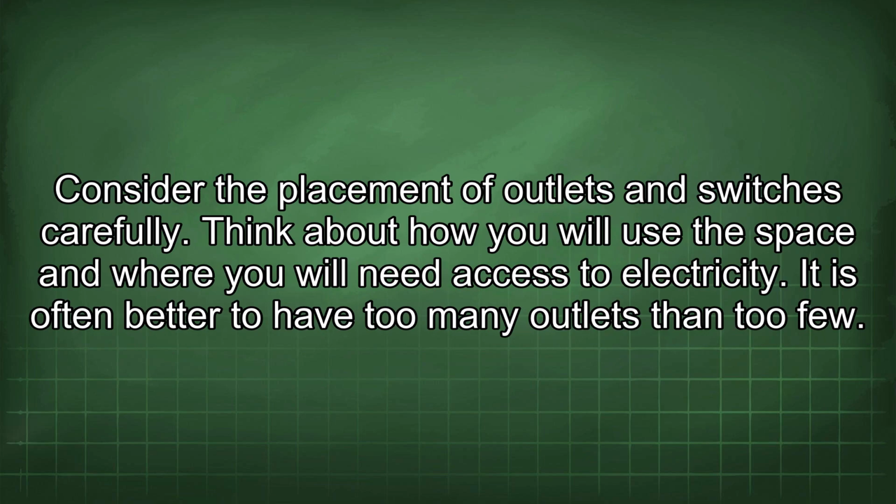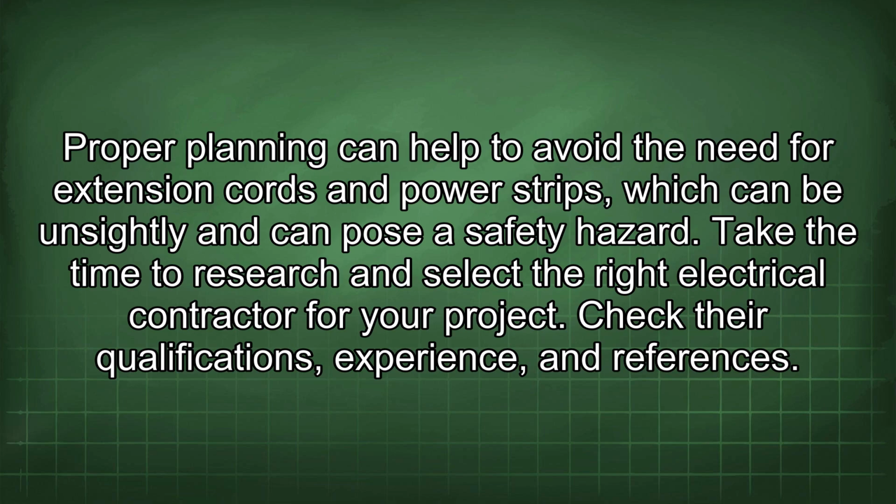Consider the placement of outlets and switches carefully. Think about how you will use the space and where you will need access to electricity. It is often better to have too many outlets than too few. Proper planning can help to avoid the need for extension cords and power strips, which can be unsightly and can pose a safety hazard.